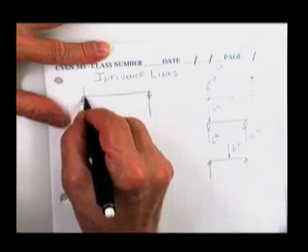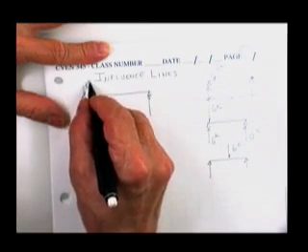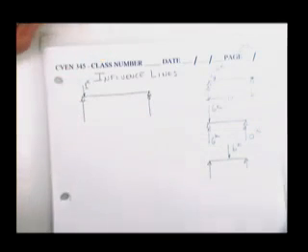And I'm going to just always use a 1. I don't care if you give it units. A lot of times we don't even give it units because if you're getting ready to use it for a Newton meter kind of thing, well, then you don't want the kips running around loose. The influence line tells you the magnitude of whatever you're looking for, depending on where you put the load.